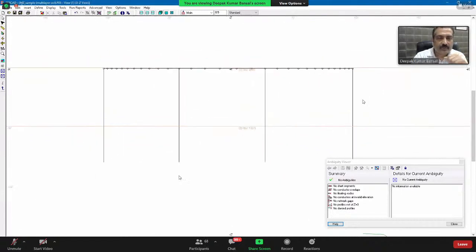You saw in the graph that leakage current density in amperes per meter is less here and very high here because the earthing resistance is very low in this area and very high in this area. So current tends to pass through the low resistance area to the remote source.